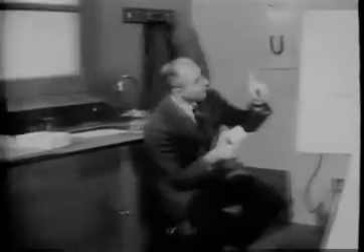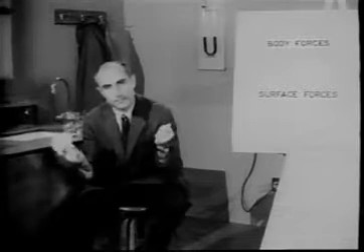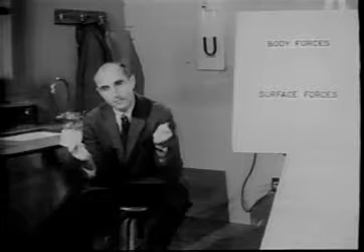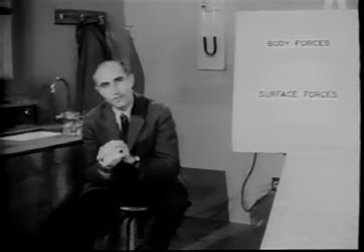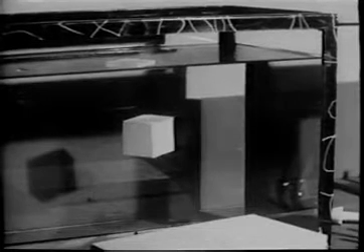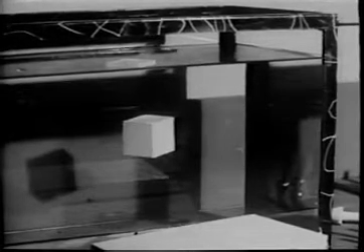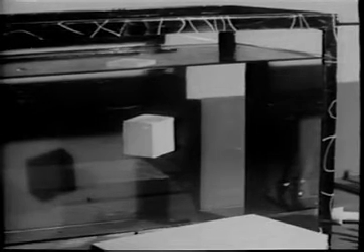While many different kinds of forces may act on this particle, they may all be put into two categories: body forces and surface forces. Body forces act at a distance: gravitational, electrical, and so on. They act on the bulk of the material, hence the word body. If this cube were a particle of water in a quiet reservoir, it would be pulled downwards by the force of gravity. But the particle is motionless, so some other force must be present to counterbalance the weight. This other force is called the surface force.